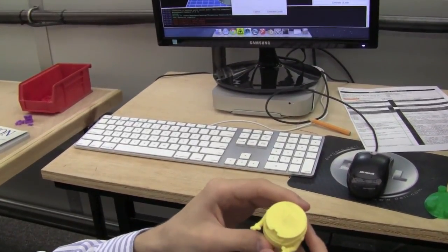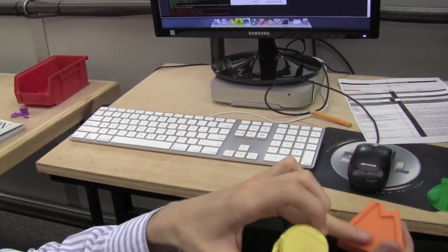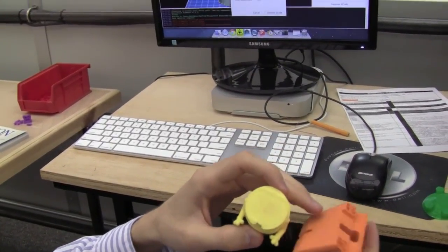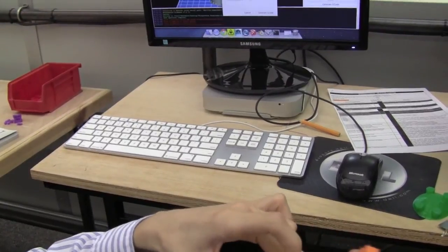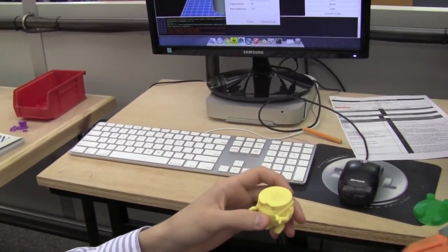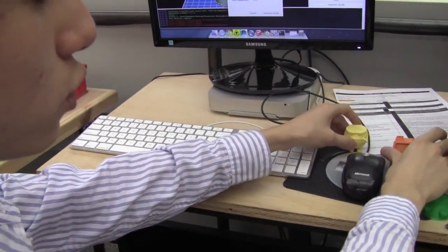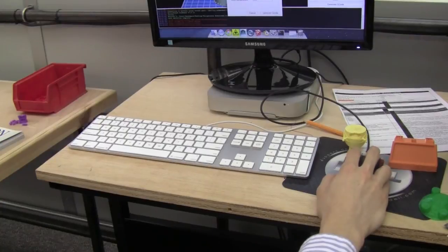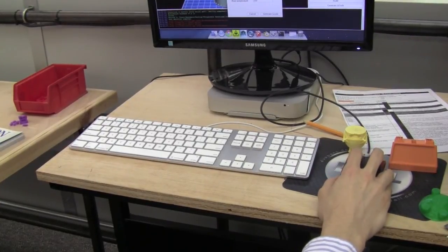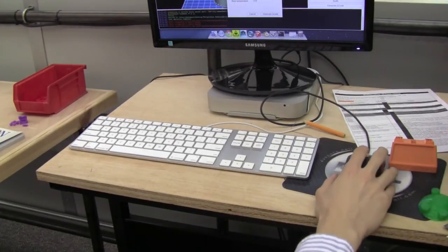So then you have a much smoother print, which is like this, where you can actually see it shine because the layers go together so smoothly. You can actually feel it. It's incredibly smooth. This is one of my favorite prints because I printed at 45 millimeters a second, which is why it came out so smoothly. Whereas if you were to print even at 70 millimeters a second, it would still come out rough. Maybe not as rough, but it'll still come out rough like that.